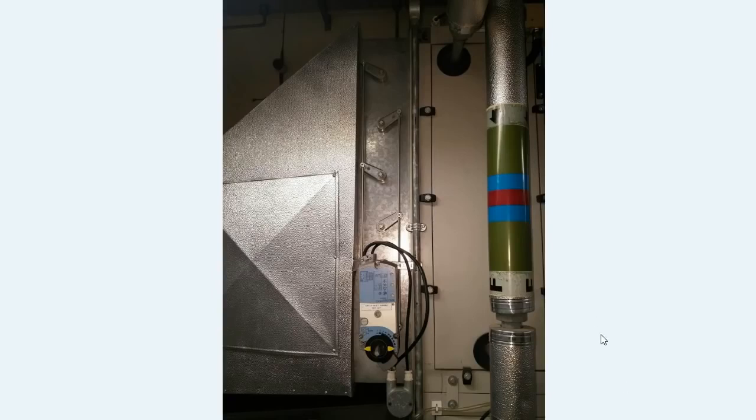And this is just a photo of one of the control units for the dampers on an AHU, and so this is being sent a controls signal to tell this to change its position, and that's a small motor inside which is going to turn this, and that causes these rods to rise and fall either way, and that will change the position of this rod here, and on the inside of the duct is the damper.